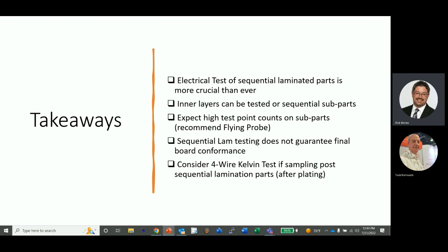Then you have some sort of identification on that panel, and it goes into a verification room where verifier operators double check. There'll probably be some false calls, and a lot of good panels, but the false calls still need a human to look at and validate. And if it's not right, you can push a button and kick it off the automated line to go for a closer review.